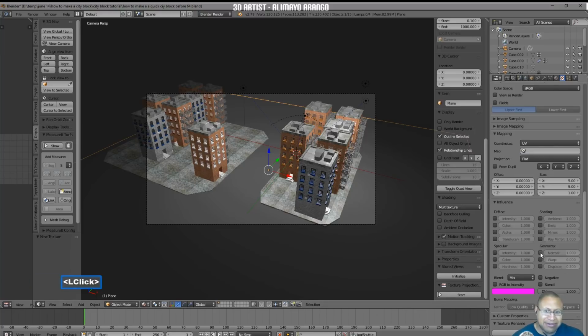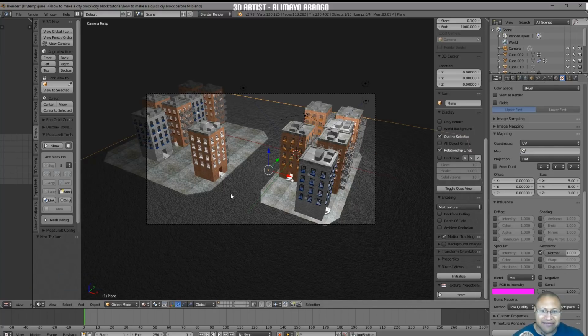Now I'm going to click geometry. And now this is very rough, too rough. So I'm going to click this normal and then select 0.1 and then enter. So now I have roughness on the street with the color that I want. And normals are a way of basically making it look like you have geometry that you don't. So if you're in a situation where you want roughness, but you want the color of your material, this is one technique that you can use.